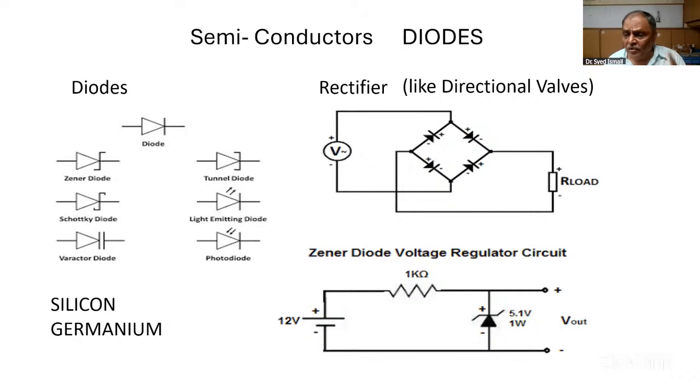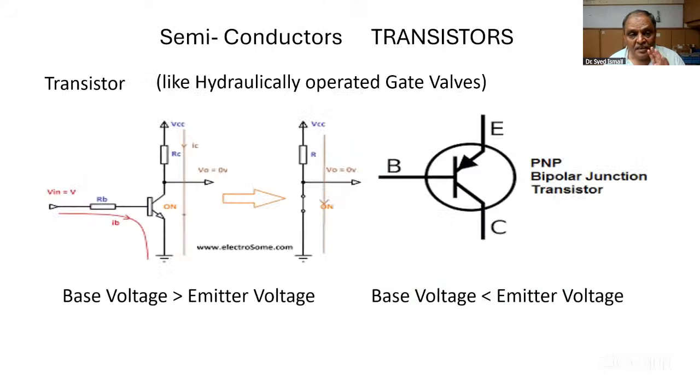For example, when you connect a solenoid, you must check whether there is a diode or not. You must ask the person. Otherwise, the solenoid will blow, your electronics will blow. A simple thing, but many electrical engineers also forget to put it in. So you must remember a diode is a semiconductor. So we need it. That's all.